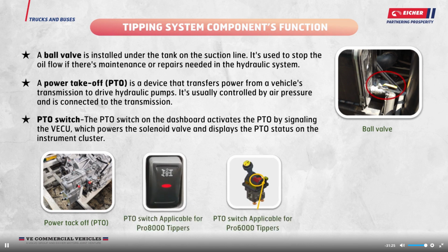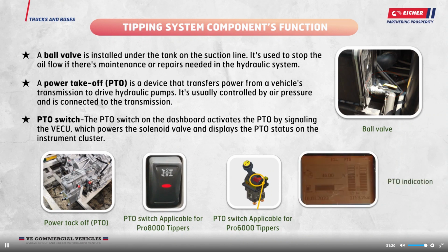PTO switch. The PTO switch on the dashboard activates the PTO by signaling the VECU, which powers the solenoid valve and displays the PTO status on the instrument cluster.